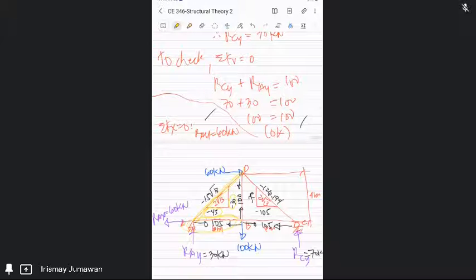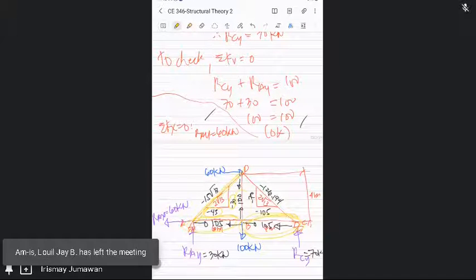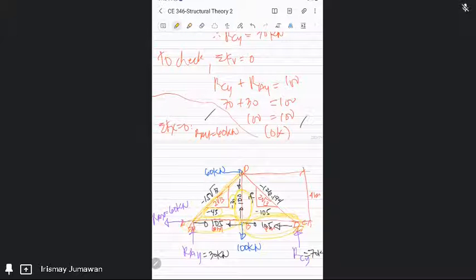Okay, next I go to B. So I balance 105 tension. The 105 balances with BD, the other member. So tension 105. Okay. Then for 100, you can go to joint D and look at joint D. What is your unknown value at joint D? It is the X component or the Y component of member